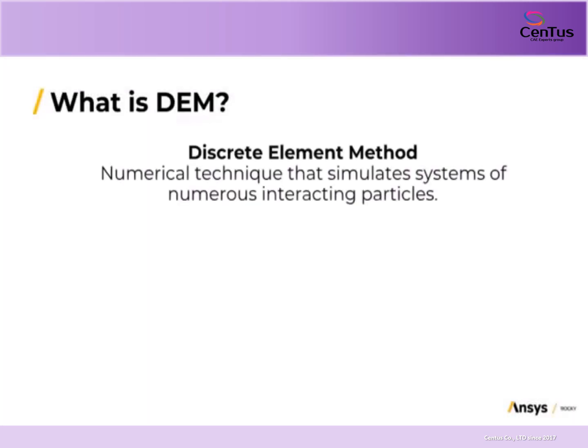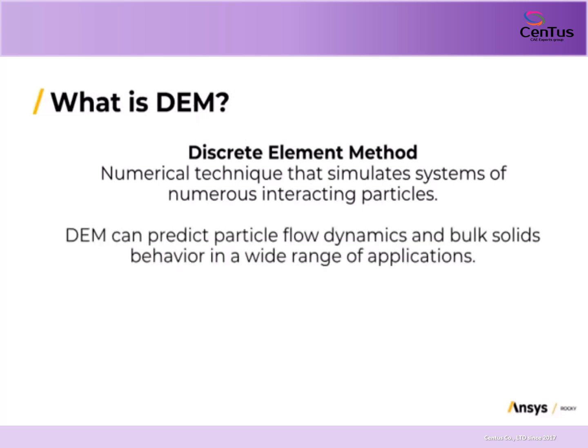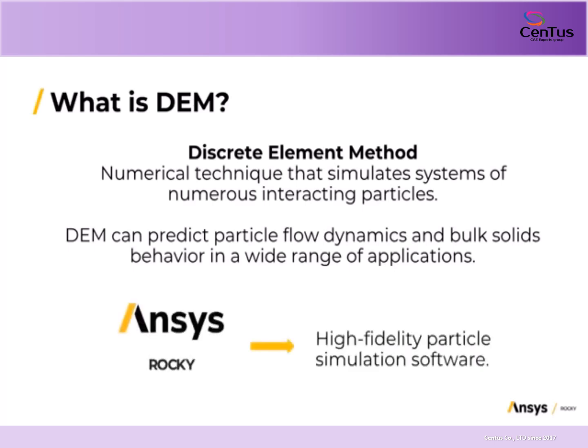The Discrete Element Method, or DEM, is a powerful numerical technique that simulates systems of numerous interacting particles. By incorporating various types of forces acting on each individual particle, including the contact forces, DEM can predict particle flow dynamics and bulk solids behavior, such as segregation, flow patterns, or clogging, in a wide range of industrial and engineering areas. It is the method used by Ansys Rocky to process its particle simulations.